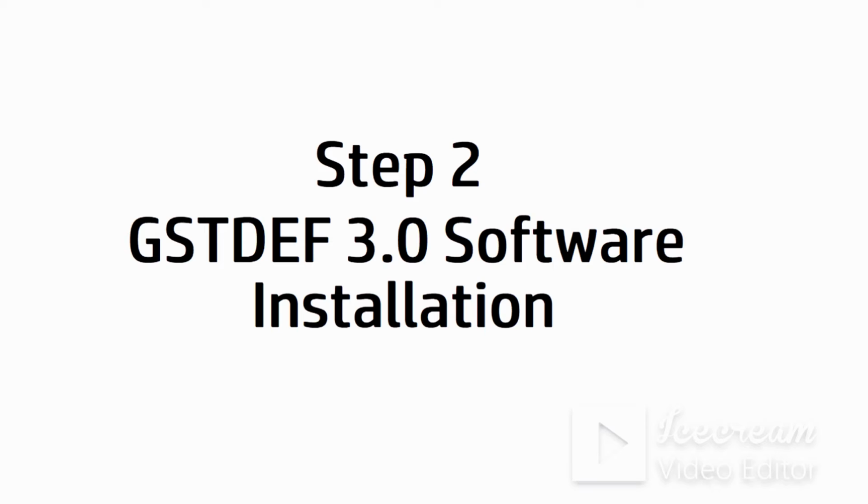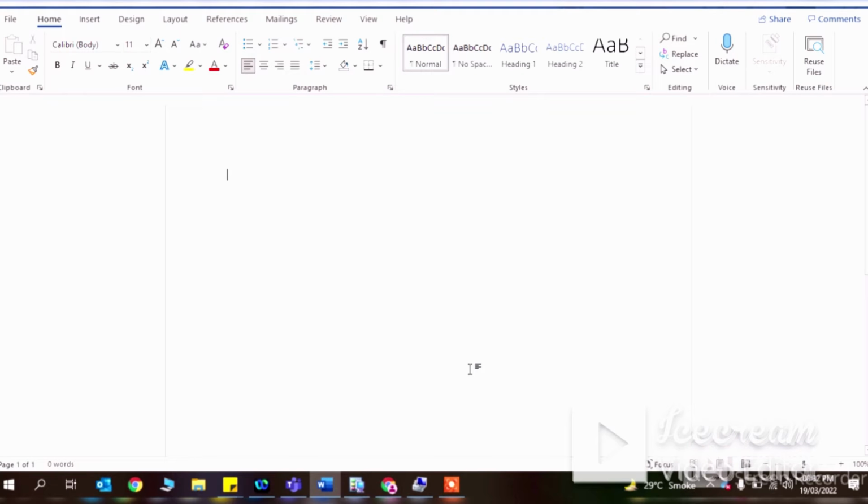Now we are going to see how to configure the GST 200 panel using that software. Once you connect the card and complete the Autolearn process, if you restart the panel, the first display will show "Color CRT OK". If we get that message the first moment you switch on, that indicates that the card has been taken by the panel. That is the first indication. Then the panel will boot up normally.